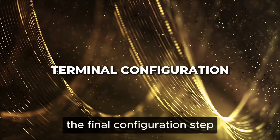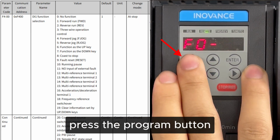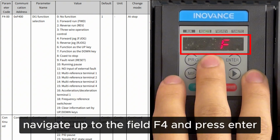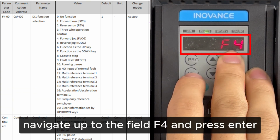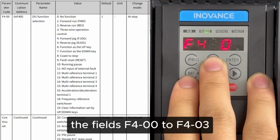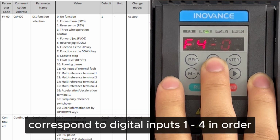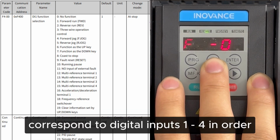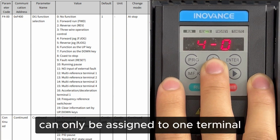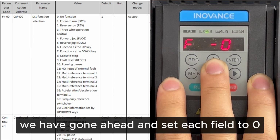The final configuration step is to program the functions of each terminal. Press the Program button to return to the main programming screen. Navigate up to the field F4 and press Enter. The fields F4-00 to F4-03 correspond to digital inputs 1 to 4 in order, and each function can only be assigned to one terminal. For the video's purpose, we have gone ahead and set each field to 0.